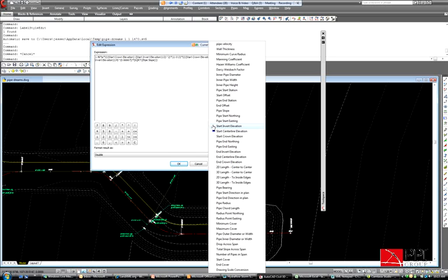In this case, it's listing a property that you should be able to bring in here, which would be the inner pipe diameter. You'd think that would be what you'd want to use, or there's even a pipe radius down here highlighted, and the pipe diameter up here. But I found that those don't actually work when I bring those into the expression, for whatever reason.